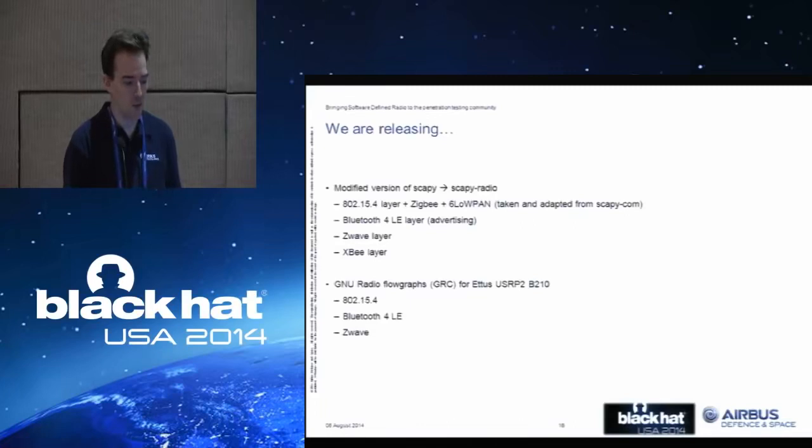Just be careful, if you want, for example, to modify the GRC files to work with the HackRF or the BladeRF, all you have to do is run GNU Radio Companion, open them, and change the UHD sink and source blocks, which deal with the USRP, with gr-osmosdr blocks, which can deal with a lot of other devices. So it's as simple as changing 2 blocks.